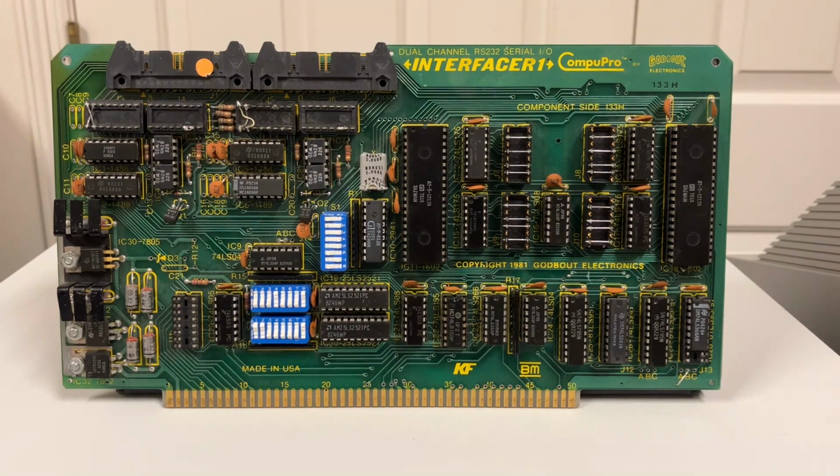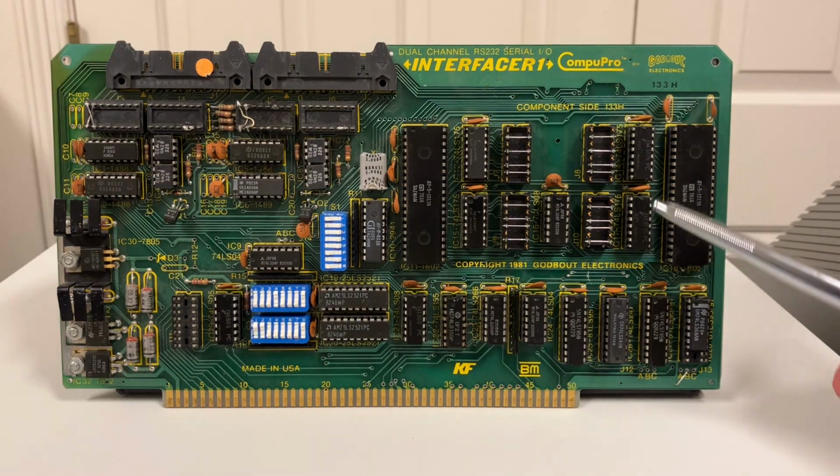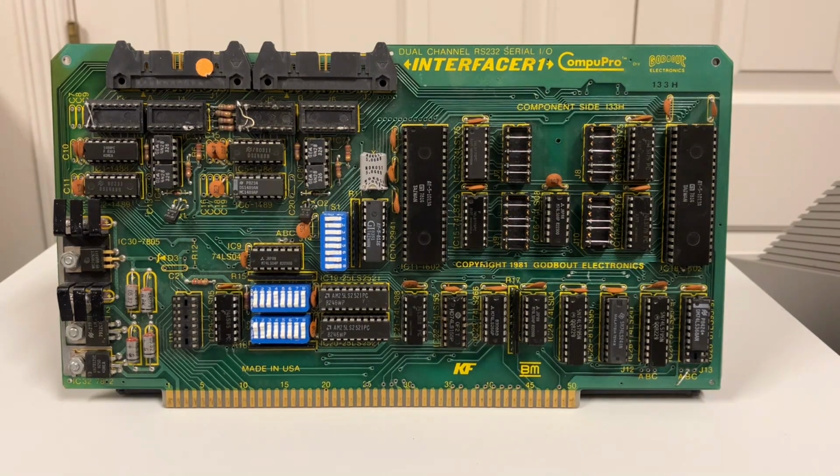Now what's interesting about this is those jumpers don't just tie to +5 or ground. Instead, they connect to these 4-bit flip-flops to get those 5-volt or ground signals. And at reset and at power on, those go to a defined state, so we always know what these jumpers mean after a reset or power on. However, those flip-flops can be written with an out instruction, and the out address is the very same address as the status register that we read. And so if software accidentally, or software we don't know about, writes to that address, it would end up screwing up our cassette interface because it could easily change the word size, parity, etc.